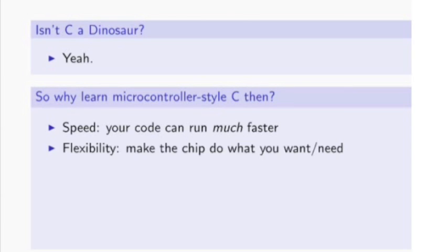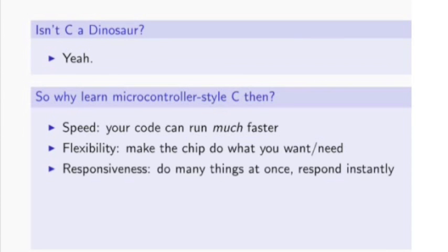You're going to have a lot more flexibility if you're coding directly yourself in C. In particular, you can make the hardware peripherals do what you want and when you want them to. You'll have much more fine-grained flexibility in configuring them. And this is what drives most people, I think, who are using Arduino to learn some C finally, is either the speed or the flexibility.